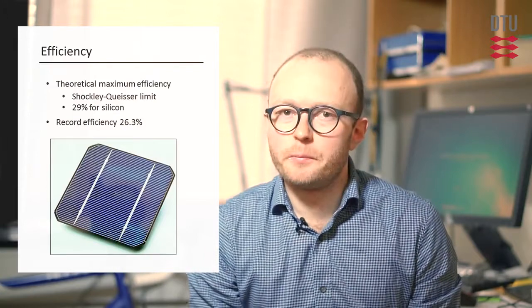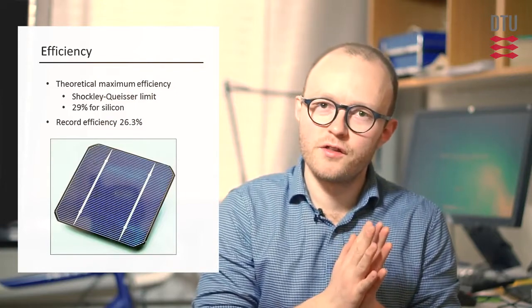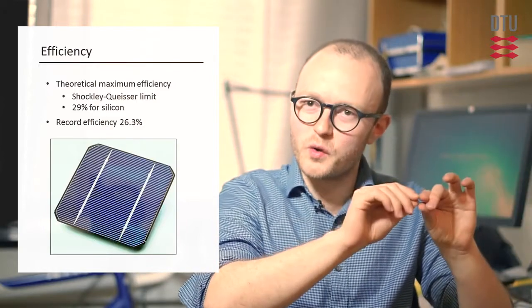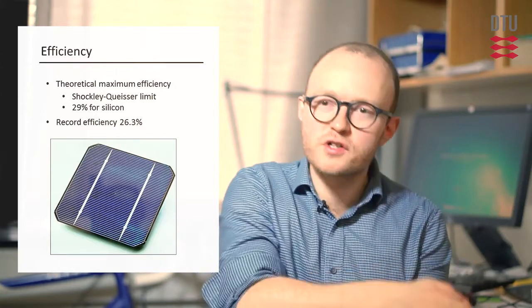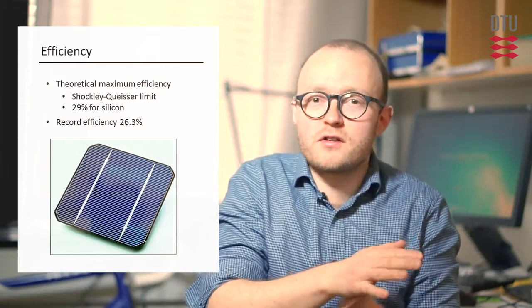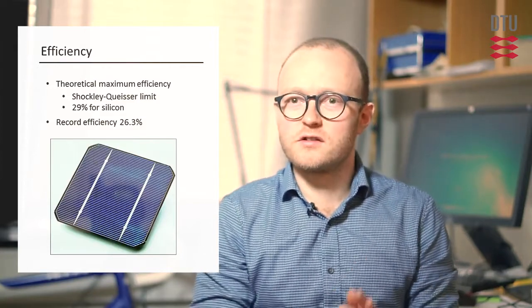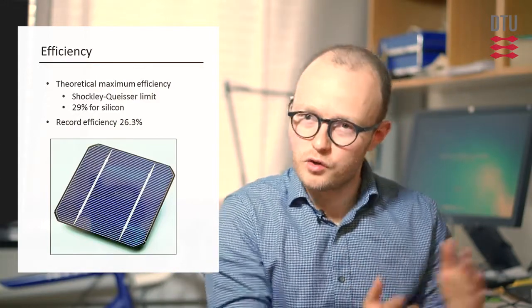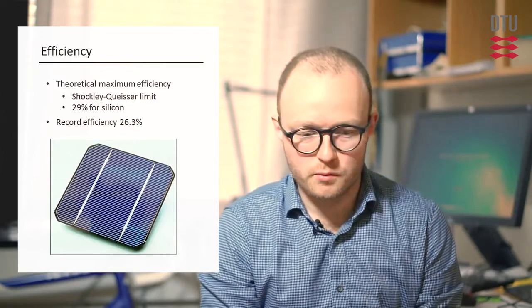There are a lot of measures actually being put into producing thin silicon wafers, and with that I don't mean thin film silicon as in a few hundred nanometers grown amorphous silicon layer, but I actually also refer to monocrystalline silicon wafers being grown or produced at a thickness of, say, 50 micrometers, on that order. That's very attractive because that thickness is just enough to get the ideal optical properties if you have perfect light trapping, good texturing, and so on. And it's ideal electrically in order to collect the charge carriers being produced.